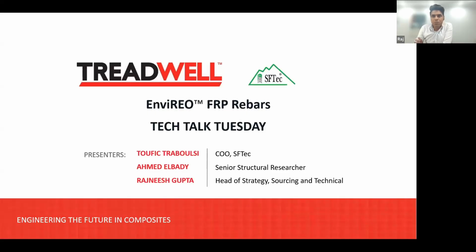One of the reasons people ask about FRP rebars is what's the advantage? Now, I like to start this with a problem. Given the geographical location of Australia or other countries which is susceptible to moisture, water, the structures are faced with corrosion problems that reduce design life, because the corrosion in the rebars or the reinforcement makes it less usable over a period of time.